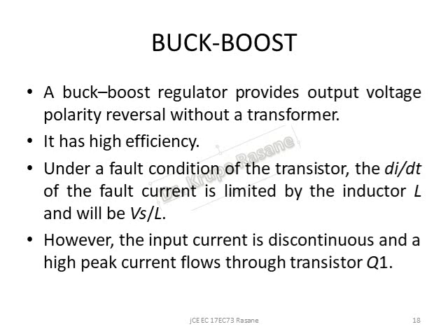So, the buck boost regulator provides an output voltage polarity reversal without a transformer. So, we are getting an output which is reverse voltage of the input. It has high efficiency, and under a fault condition of the transistor, if the transistor short circuits, then the current increases.